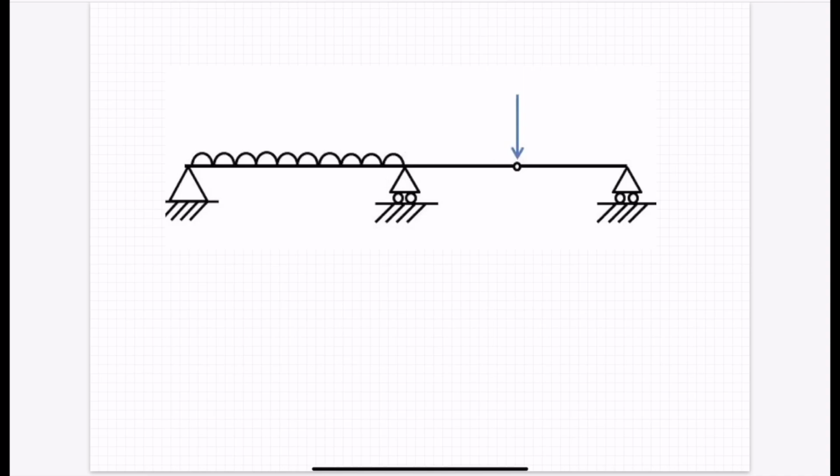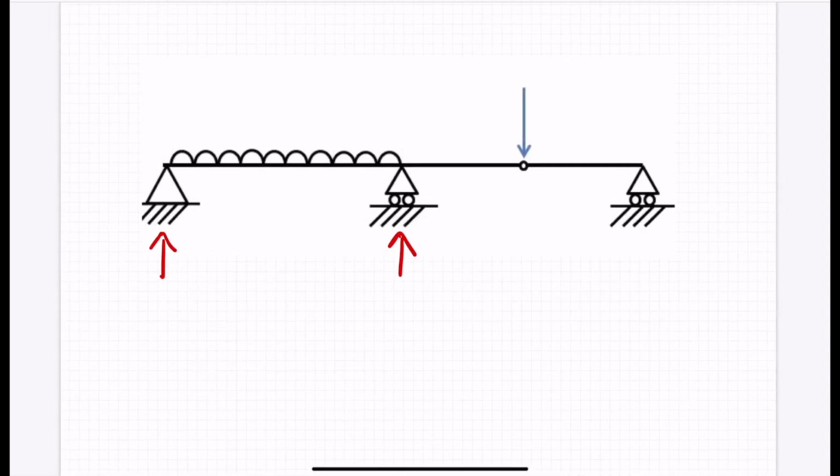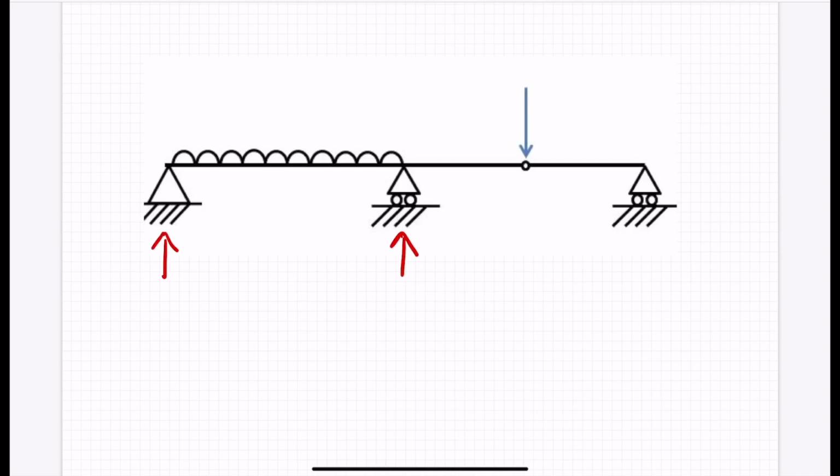Here's another beam. We're not given any lengths or magnitudes of the forces, so we're just going to have to work with this. Straight off the bat, we need to draw the reactions. I will draw the first two, but with this right hand one we have to be very careful because we have a pin here. Bending moments are caused only by external forces or reactions; if we cut anywhere along this beam, for there to be any bending moment, there has to be a vertical reaction.